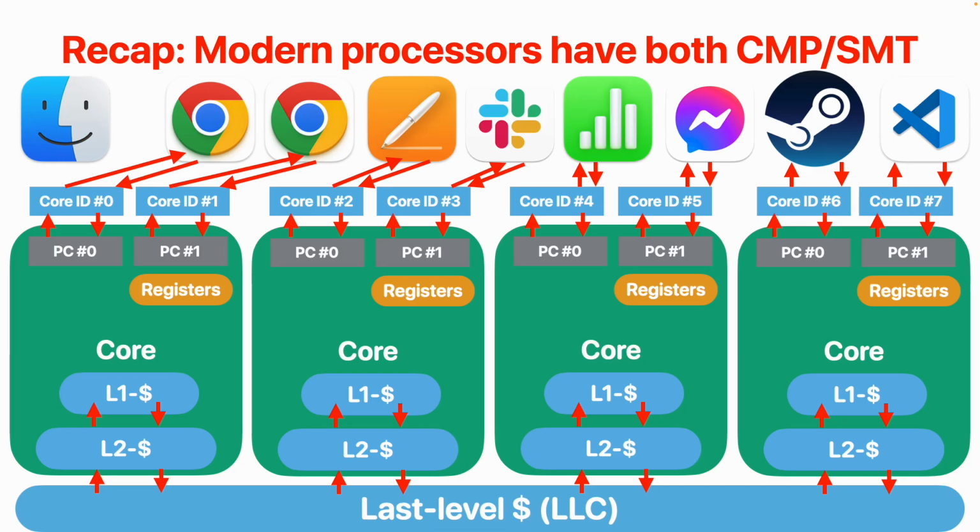All right. So in the last lecture, we got to know that modern processor architecture is pretty much like this. For each processor, you have a superscalar pipeline with multi-issue capability, with out-of-order execution capability, but still maintaining the correctness of your program through the reorder buffer.